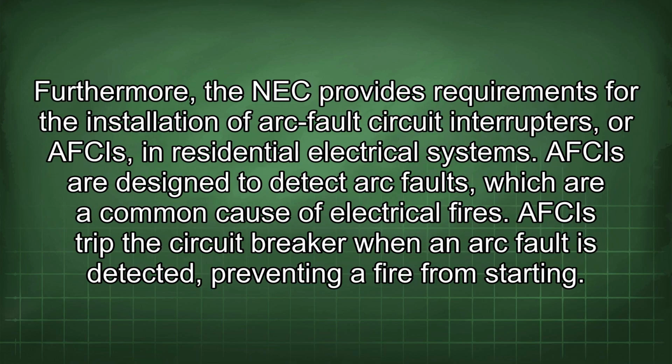Furthermore, the NEC provides requirements for the installation of arc fault circuit interrupters, or AFCIs, in residential electrical systems. AFCIs are designed to detect arc faults, which are a common cause of electrical fires. AFCIs trip the circuit breaker when an arc fault is detected, preventing a fire from starting.